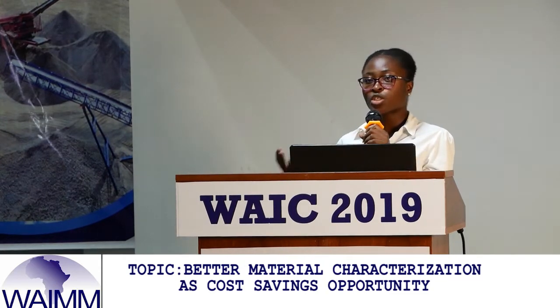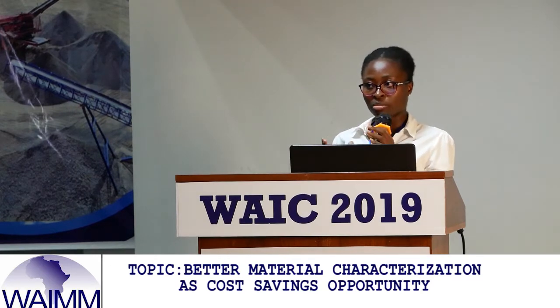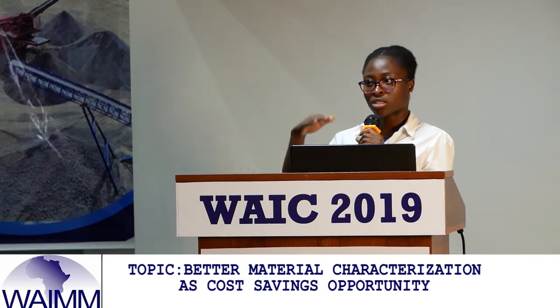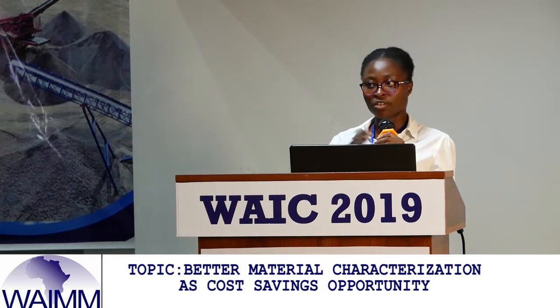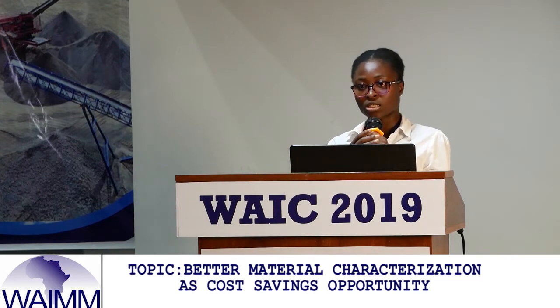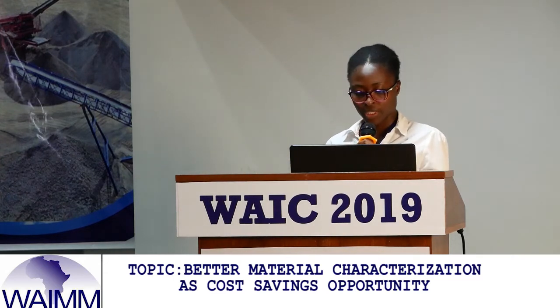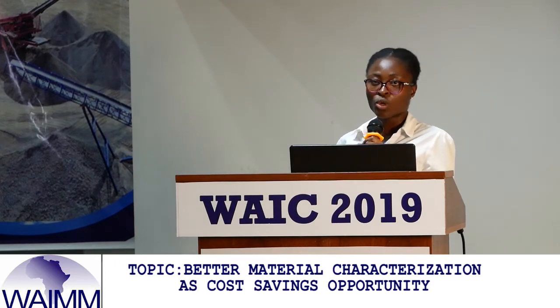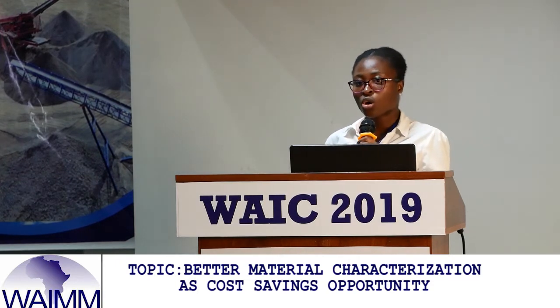So that means we can fit more tailings into the same space of a TSF. So instead of building a higher TSF, we don't need to build something so high. We just build a smaller TSF, and we can keep more tailings in it over a certain period of time. We also get to decide whether we can do an upstream raise or a downstream raise.